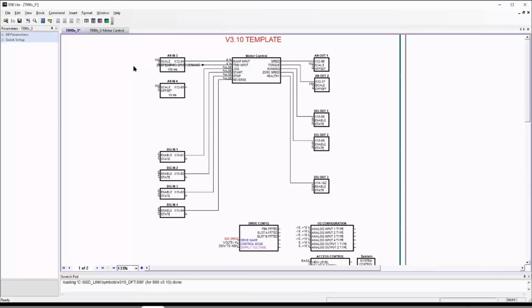What that means is that even though this is a serial link between the drive and the computer, you can pre-trigger a scope on a certain condition, and then when that condition happens, the drive captures the different values you want, puts them in its memory, and then loads them out to this tool. So you get a snapshot of what happened when your trigger happens.